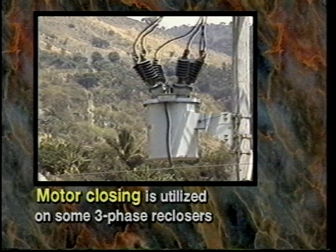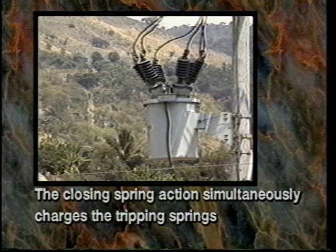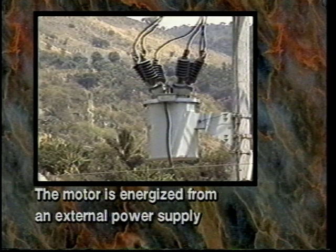Motor closing is utilized on some three-phase reclosers. The motor charges closing springs and forces their over-toggle to close the recloser. The closing spring action simultaneously charges the tripping springs. The motor is energized from an external power supply.